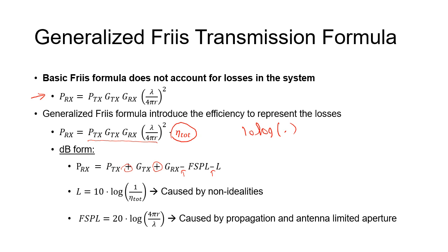And the free space path loss, FSPL, is determined as 20 log 4 pi R over lambda. Here it was squared before. This was actually 10, and if we use the log characteristic, it will be 10 times 2, which is 20. Just to note, we know that the gain is in dB, loss is also in dB, but a very important note is that power here is not a ratio, so we use something called dBW as a representation.